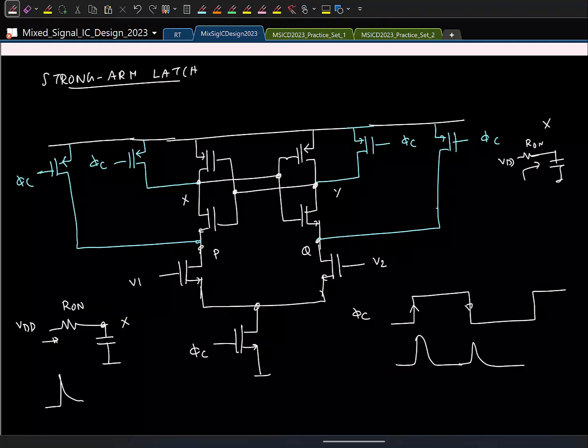So you'll have power consumption only at certain times. When do you have power consumption here? Only at the edges of the clock, right? If the clock is static, and if the input is not changing, there is no power consumption. So this is a truly dynamic circuit, the power consumption is there only if you activate the clock, which means only when the clock toggles. And the other nice thing is you just need one clock phi c. You don't need phi bar and all the business. That makes it a bit simpler.